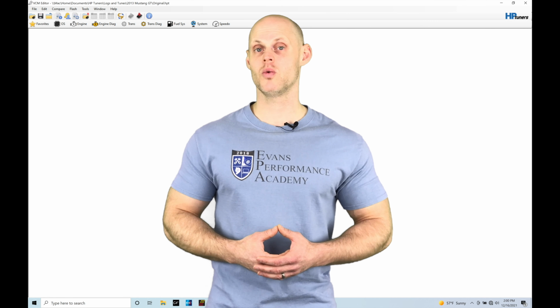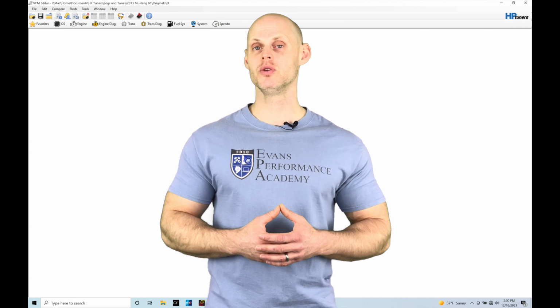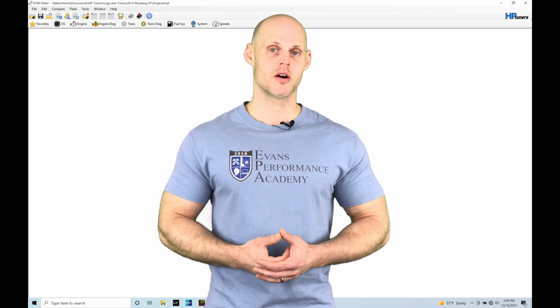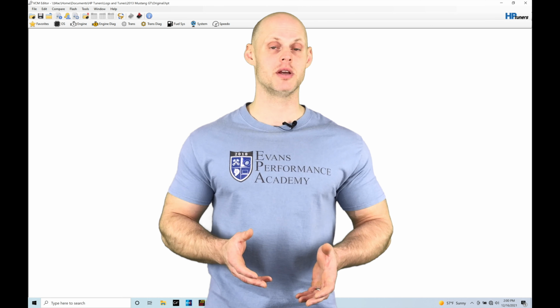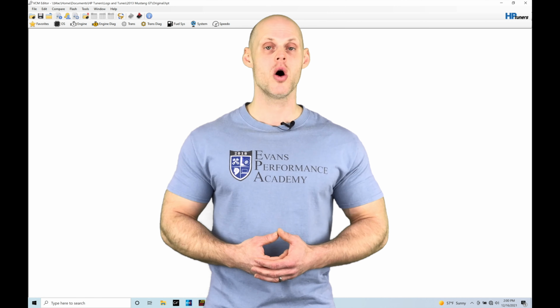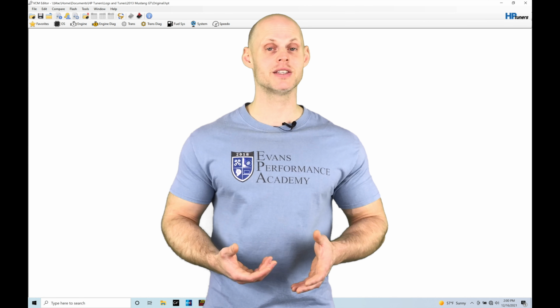In this training module, we're going to be taking a look at working with our fuel injector characterization data in our Ford PCM programming. Our fuel injector characterization data is going to be accounting for the flow rate of the injectors that we have installed in our fuel system. Also, the characteristic response of those injectors.